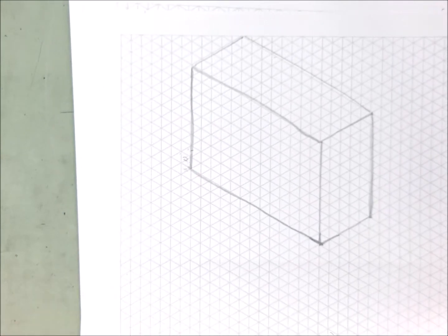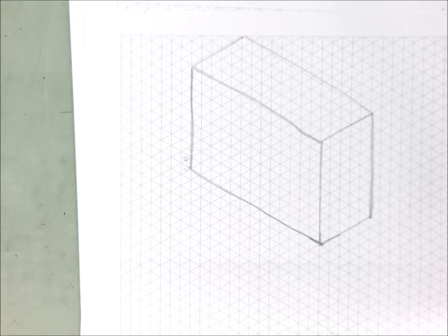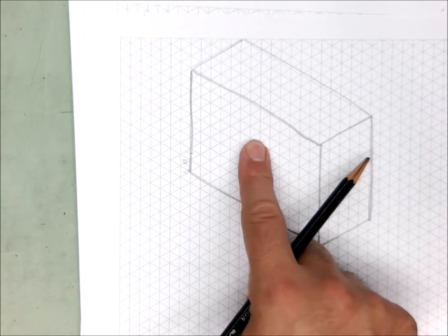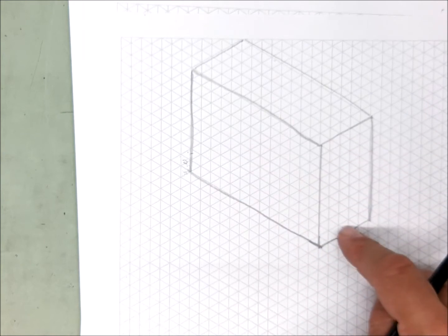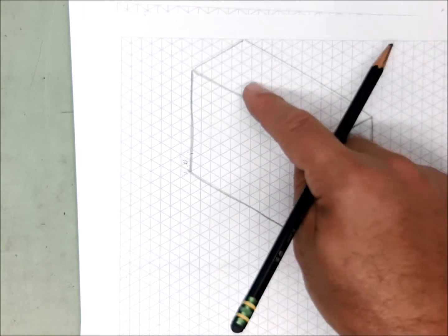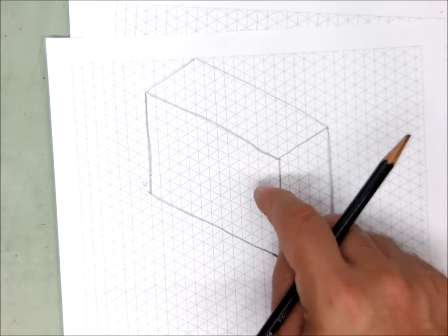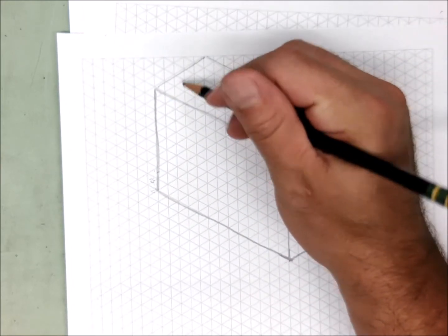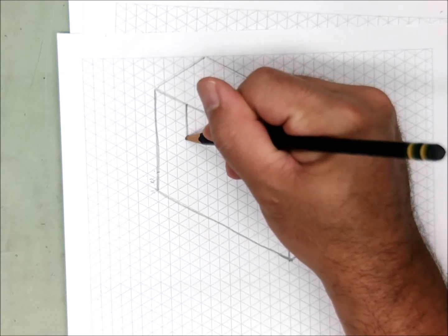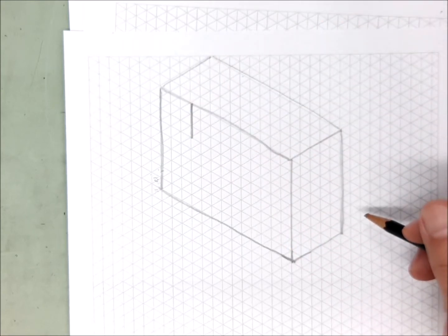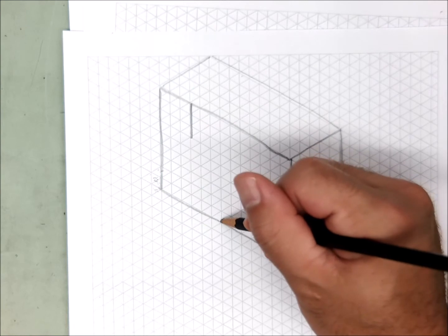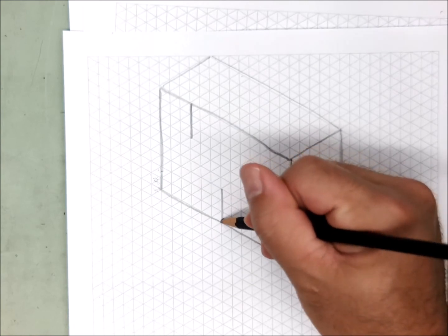Okay, so here's our block that we're going to work with. Can you identify the face or the surface that shows the shape? Well, once again, it's the front. The side is 3 rectangles, not helpful. The top is 2 rectangles and a hidden line, not helpful. What's helpful? The front. So let's try to replicate what's on the front in the 3-view drawing onto our drawing in isometric.